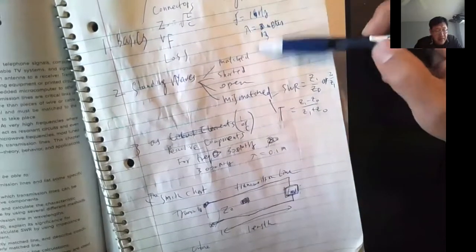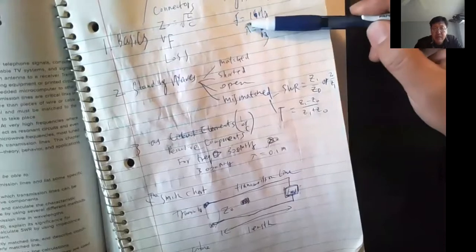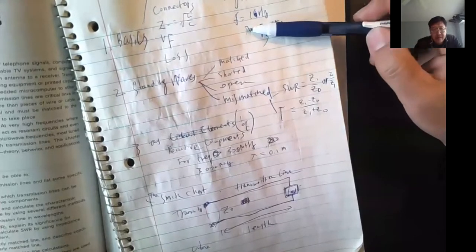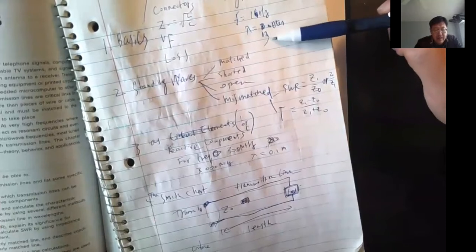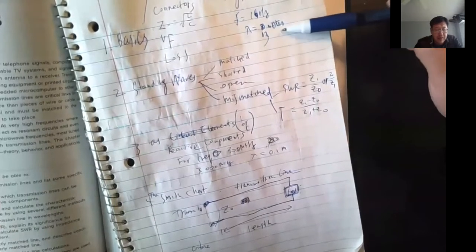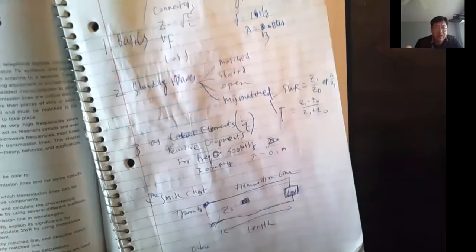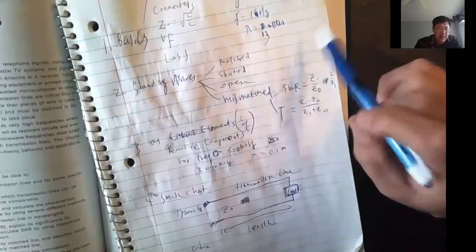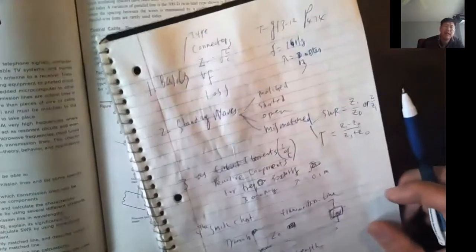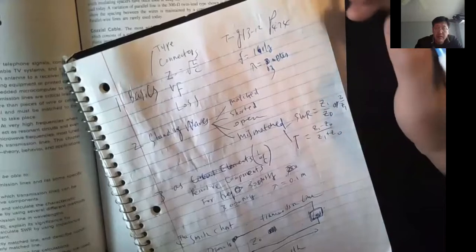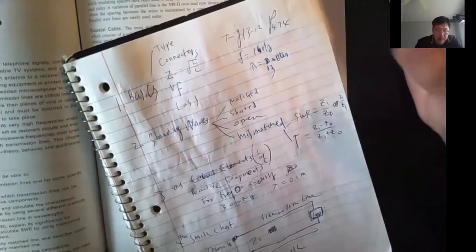But with a transmission line, with signal frequency in gigahertz, you have to, because a lot of the conductors are longer than 1 foot, 0.3 meter long. So the voltage and current can be different at different locations on the conductor. So that is why we have to study transmission lines, because something strange, something unique will happen.